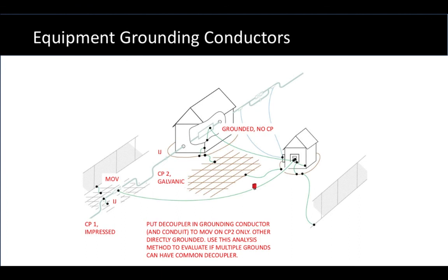But consider also that if conduit is in contact with the pipeline, it is part of the cathodic protection system up to the point of decoupling. The closer you locate a decoupler out near the pipeline, the less of that conduit run is part of the CP system, and therefore it is harder for an electrician to go and bypass it later in the future if they were to hang a clamp off of the conduit or do something with that conduit. Therefore, generally, a more foolproof system is where the decoupling points are closer towards the pipeline.